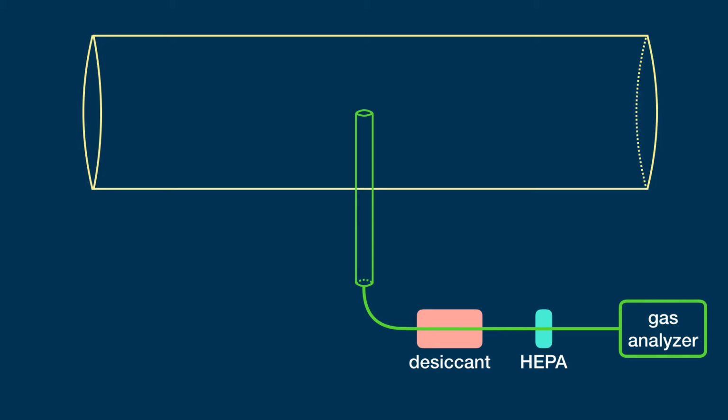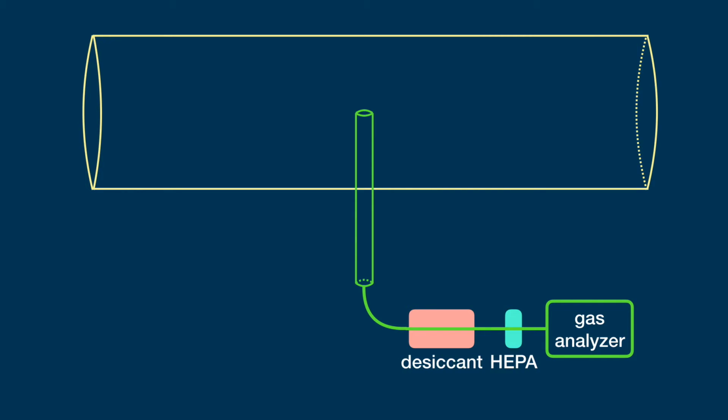The gas sampling line and desiccant bed, if necessary, should be kept as short as possible. This will help minimize the time delay between the gas analyzer sample readings and the real-time events with the cookstove, such as lighting the stove or adding more fuel.